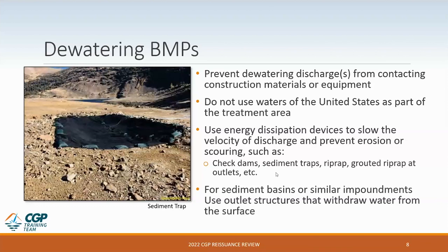If you're going to use a sediment basin or similar impoundments, it's wise to use outlet structures that withdraw water from the surface. That way you're avoiding stirring up more sediments and discharging clean water.